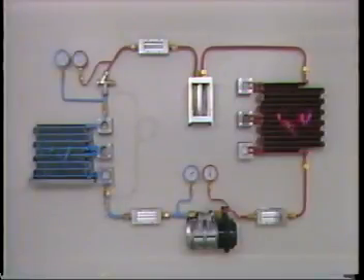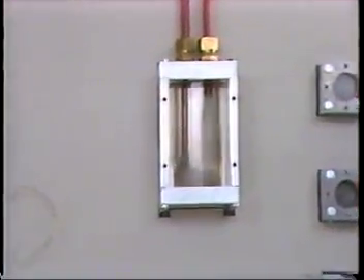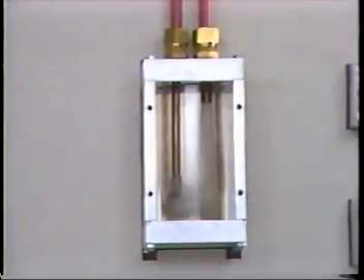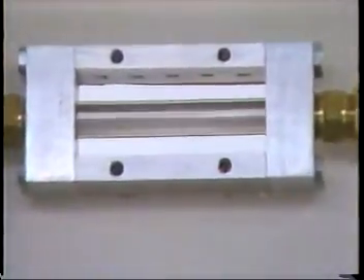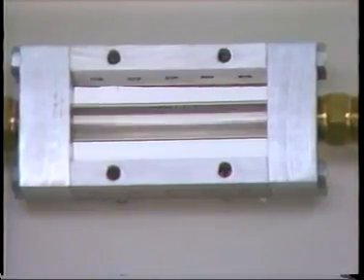You can easily imagine that the air conditioner's cooling power will be less if there is not enough refrigerant in the system. But why is this so? When the amount of refrigerant is less, there is naturally less refrigerant in the receiver and dryer unit. For this reason, much of the refrigerant is a gas when it reaches the expansion valve, as you see here.